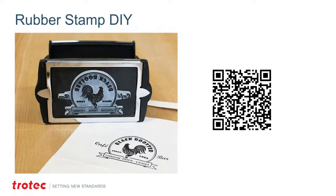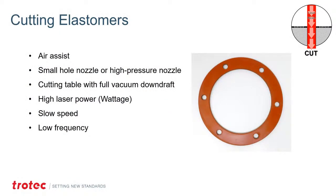But when it comes to engineering materials like that, rubber stamps aren't as popular anymore. Now, cutting it is something that is still very viable because you have the ability to cut, say, a nozzle or a gasket out of the rubber at a moment's notice. Being able to create these on demand is huge. Air assist is required, a small hole nozzle with high pressure air running through it, and a cutting table with full vacuum downdraft.